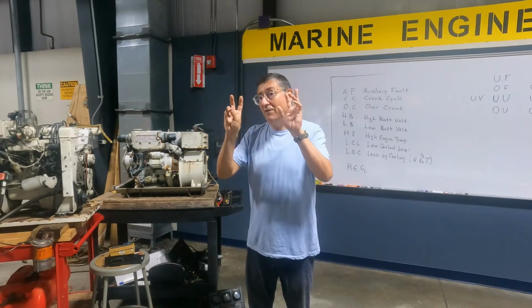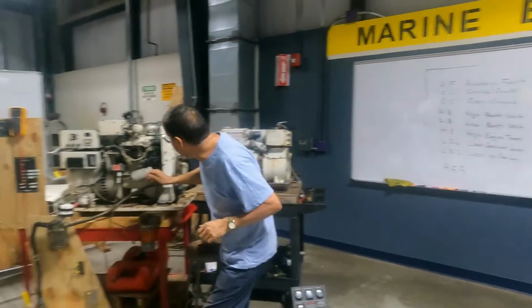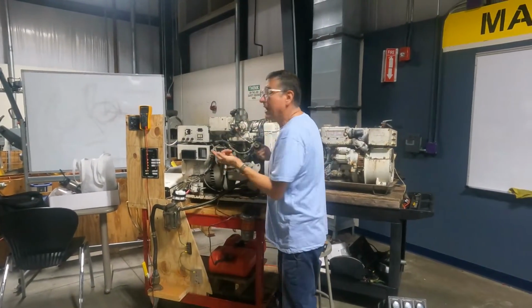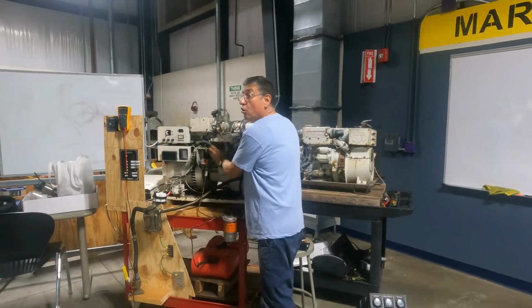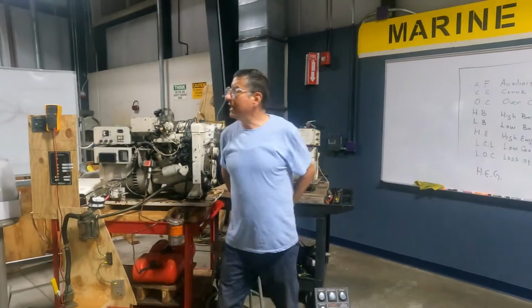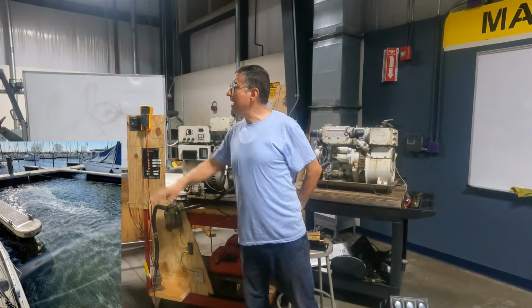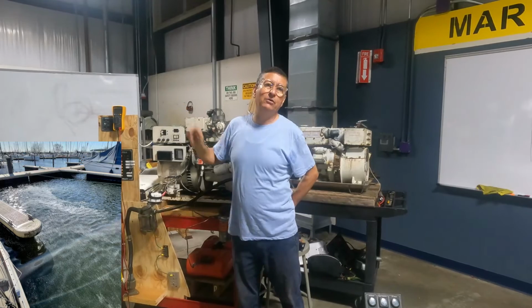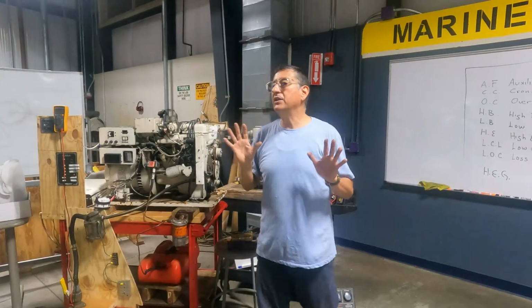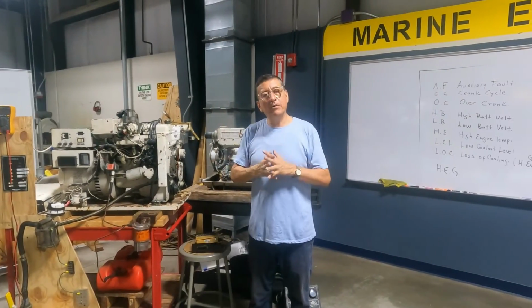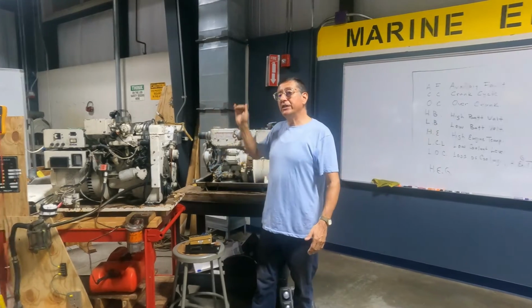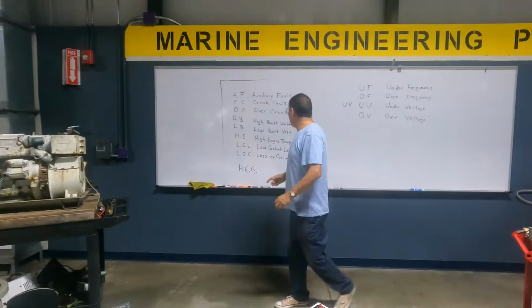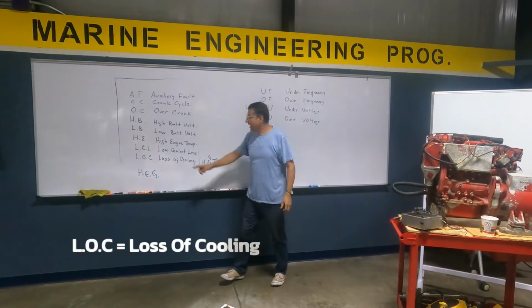What happened? You have two possibilities. The coolant is mixed with the oil. When I check the oil here, oh yeah, I have milky oil. Or let me start the generator and I check outside of my boat. Oh yeah, I see a film of coolant on the water. The coolant is going out. Both of them are critical problems. It's an internal problem in the engine. If the coolant is going down, you have a serious issue in the engine. Ready, guys? Okay, look at this.